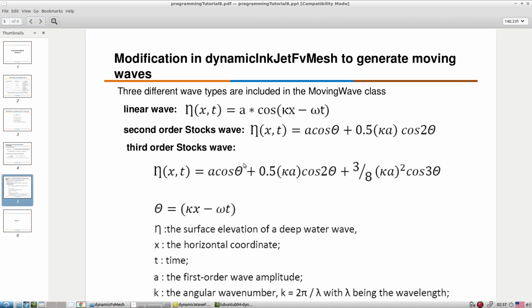Okay, so we try to use the same idea of diffusivity parameter used to absorb the mesh deformation next to the moving boundary by multiplying the calculated functions by a decaying exponential function. Okay, so we add some decaying exponential function along with this to damp out or absorb the mesh deformations. Okay, so that is the trick.